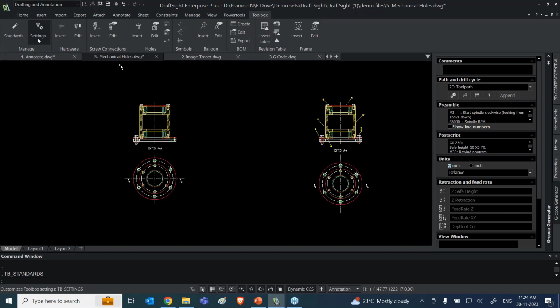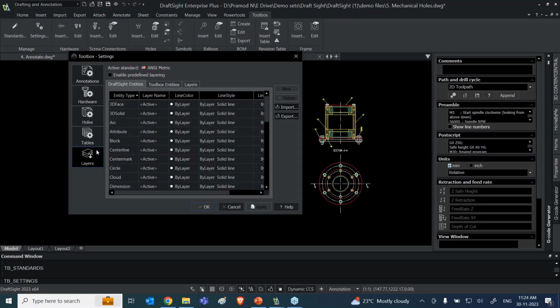And next thing is the layer management. In most of the CAD tools, layer management is one of the features that is very important when working on the 2D platform. In many of the CAD tools, once we create any particular profiles or once the design is completed, we select those specific profile entities and add them into the layers. So suppose once a drawing is created, I want all my dimensions to be in one layer. So I select the dimensions and put them on the layer. And I want some other components to be in another layer. So we do that work manually.